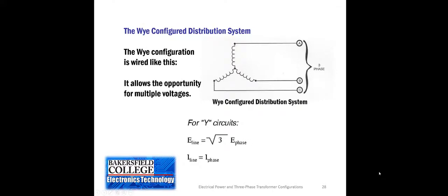Okay, so how the current works is that, let's say there is 20 amps of current flowing through each of the coils, each of the phases. Then that same 20 amps of current that flows through this one, for example, will also flow into and out of the line, the L1 connection, if that's what is connected to terminal A.